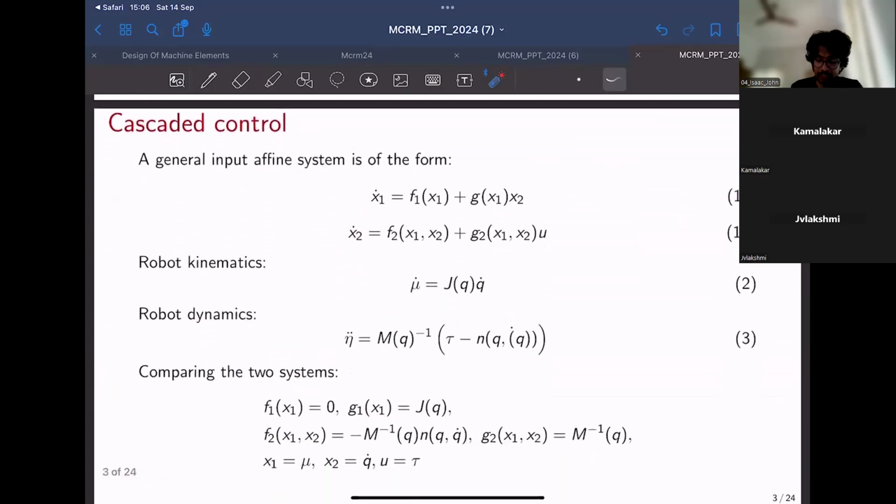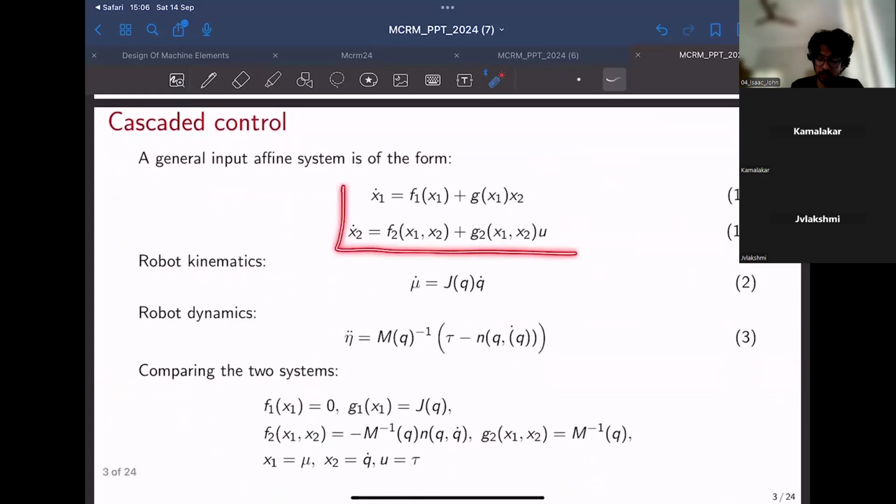Okay, so yeah, any system can be decomposed into several first order linear differential equations, and these x1 and x2 can be considered as the states of a system, and these are mostly denoted as a system vector. The standard form is x dot is Ax plus Bu, a standard state space form, where A is what we call the system matrix, and x is the state vector, and x dot is the derivative of the state vector. And this small vector over here, u, is called the control input.